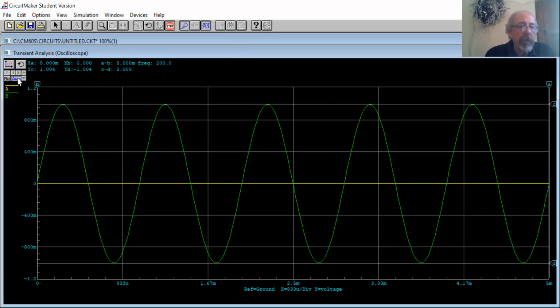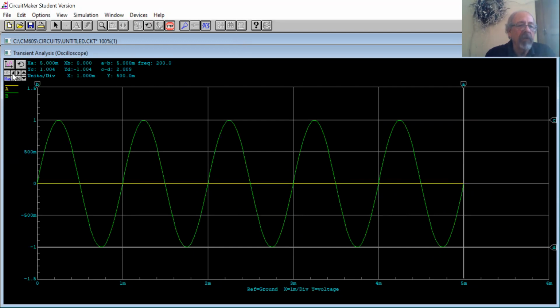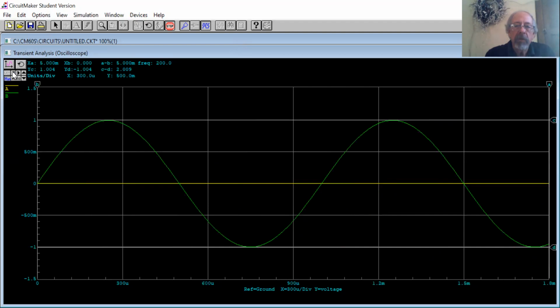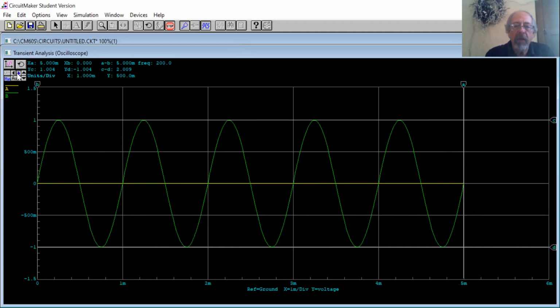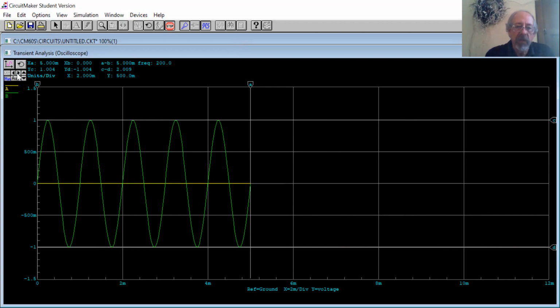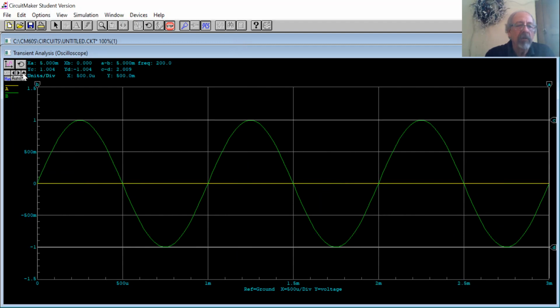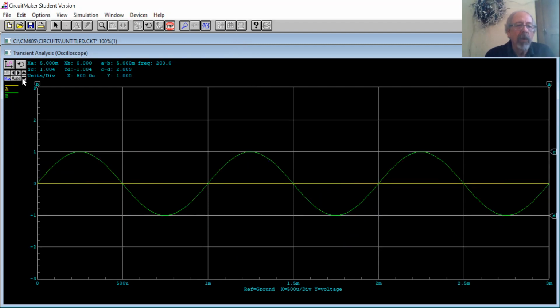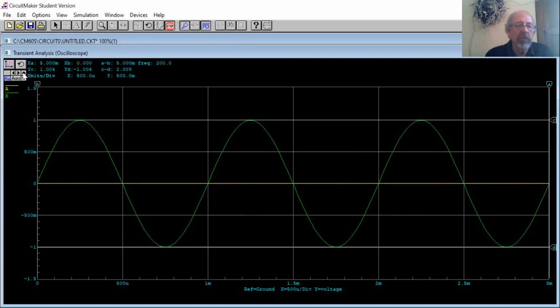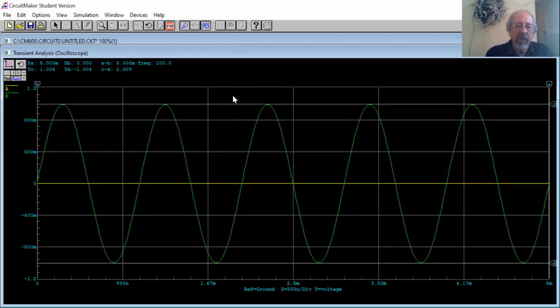Now, the scope here has an auto, so it's in auto mode right now, but there's also a manual. When I go to manual, I can take and do stuff like this, or I can stretch it out or bring it back. Now notice still 5, I'd have to take and redo this to get more traces there. So let's go back and go here. I want to make the signal smaller or bigger. I can use these little arrows here. If I want to go back, if I want to do something like this, I can click on the left click the screen. Now, can I? I guess I can't do it in this mode. Let's go to auto. If I left click on the screen, I can put a box over the signal.